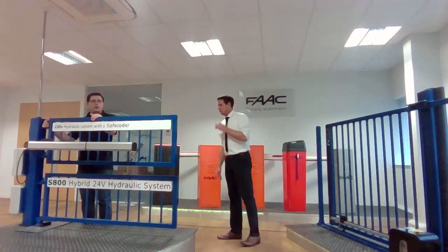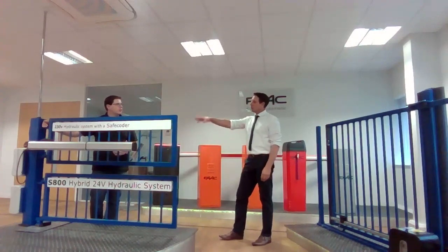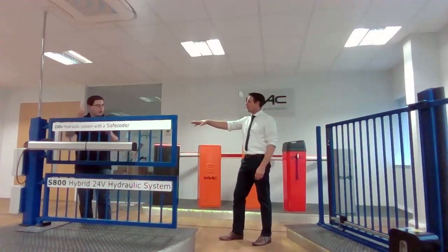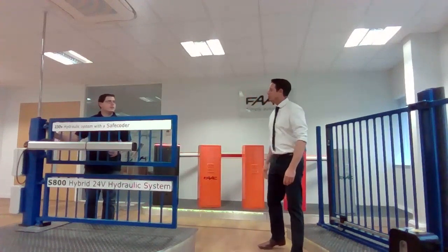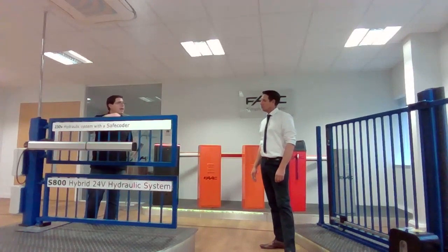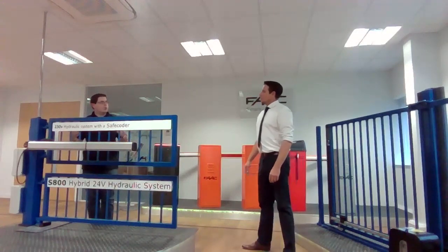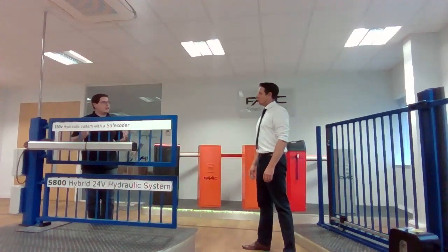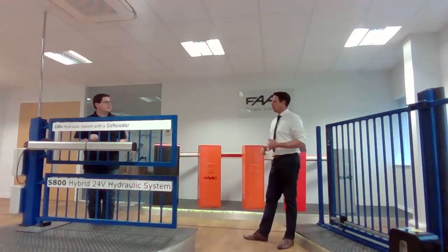Obviously, when you're doing a retrofit on an existing gate, you need to make sure you inspect the hinges, which are solid. If your hinges are like this, they're kind of ideal. If they're both pointed up, then essentially they're both holding the weight of the gate. Yeah. But it's quite common here in the UK to have one hinge at the bottom pointing up, and one hinge at the top pointing down, so you can't just remove the gate, for security. The problem with that is if the bottom hinge breaks, your gate falls off. And it's really gates falling off.